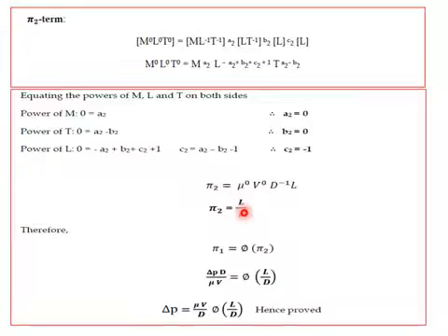You know that the ratio of two length terms is one of the pi terms. You could have written it directly, but anyway we have solved it. That's the reason why we get L by D, and why the powers of a2 and b2 are 0. For d we got c2 as minus 1, so it is L by D. Now pi 1 is a function of pi 2, so substituting the pi 1 term and pi 2 term here and rearranging, we get the required equation.